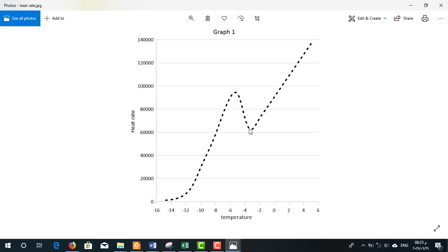until we begin freezing, because freezing emits heat to the surroundings, so we have an increase in heat transfer here until the peak. Then the heat transfer decreases because the temperature decreases, and heat transfer by convection or radiation decreases, and the latent heat decreases until near 0.